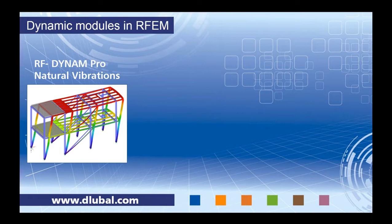Here you can import masses from load cases, you can create mass combinations, and in addition you can manually define additional masses, not only at nodes, but also on members, surfaces, lines. We can also include any initial conditions such as axial forces, stiffness modifications, and a little bit more, and I'll be showing that today as well.